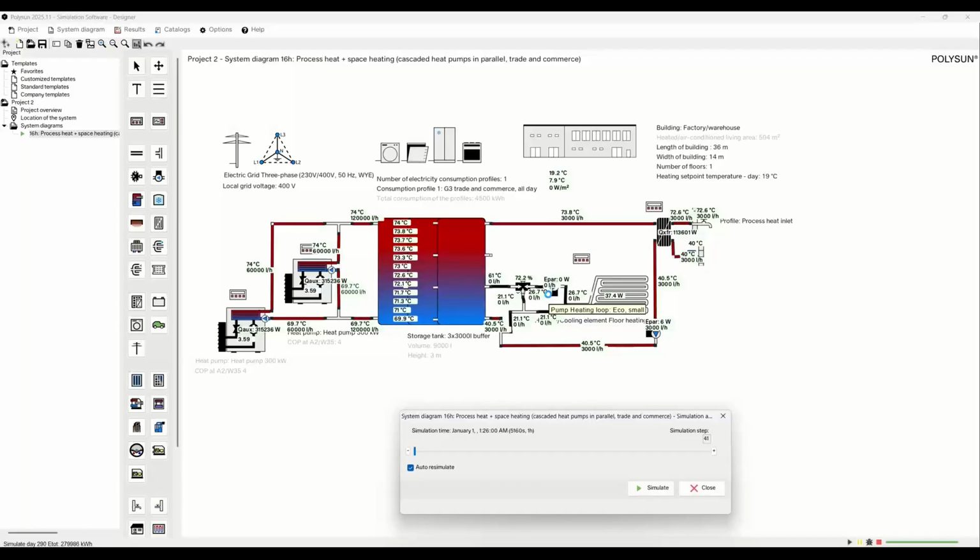Here now we have this parallel system, which focuses on redundancy. So now you have 2 heat pumps, they're sharing the load. Cascades are really used for high fluctuation of loads, and they share the load, and it's a redundant system. So if one stops to operate, you still have the other one, and also as there are 2 heat pumps running, they can always run in the optimal, in the sweet spot when running at partial load.